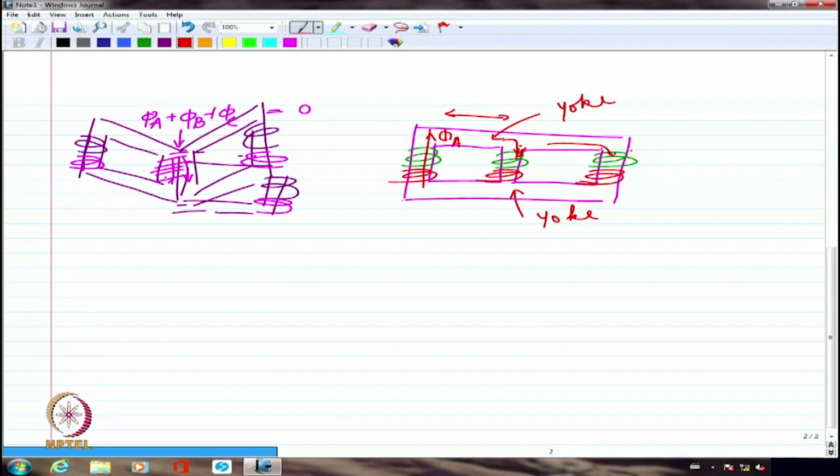Why do we need that? Basically, we are connecting ends of the wires of individual coils at the end of the day. So why do we need this yoke? Why do we need a magnetic circuit amongst these all? If you don't have a magnetic circuit, where is the question of electromagnetic induction? Basically, individually, A is an auto transformer, B is an auto transformer, C is an auto transformer, and we're linking all of these two wires. But the magnetic lines that are actually coming up because of the current flowing have to find a closed path. How will they find a closed path? If you don't provide any other path, then it will go through the air.